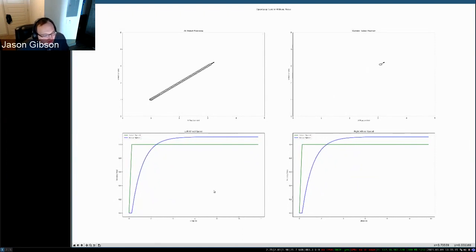This is the most perfect ideal world you could ever ask for when you're just doing open loop control, which essentially means you're just setting a velocity. If the world was perfect and there was no friction and all these things didn't exist, this is essentially what you'd get. You'd set some sort of power, and that would correspond to some sort of curve that would decay out to the point where you're just hitting a constant velocity and you'll stay there.